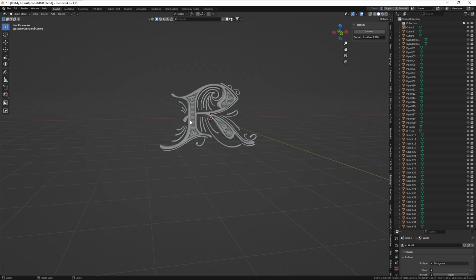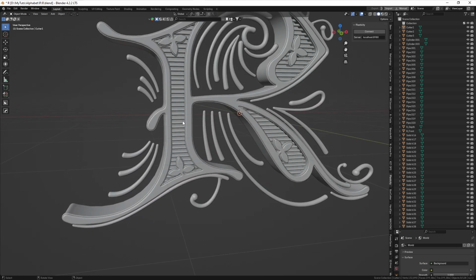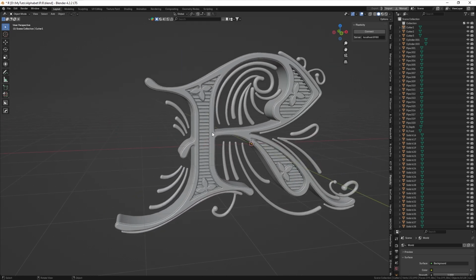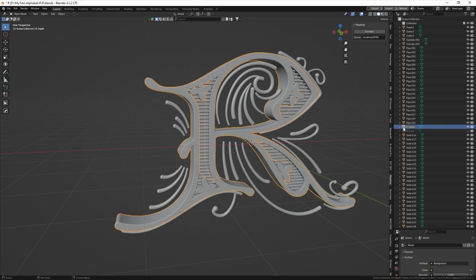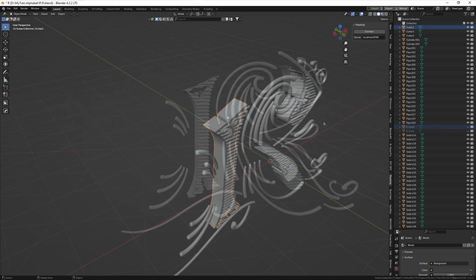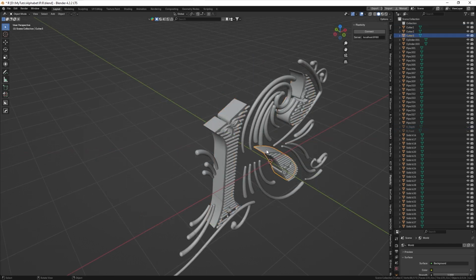The second thing is grouping all the small parts, and therefore I am hiding first of all the big ones, which I have named already in Plasticity. If you haven't named them, you can do it now. Select the big part, for instance this one, press F2, then you can give it a name and hide it, pressing H. So the shortcuts are the same for hiding and unhiding. This one I called R depth height. So this is cutter 1, 2, 3. Yes, I have named them that way so we can hide these.